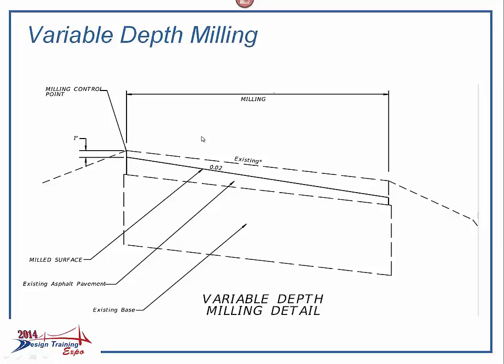The behavior of the subassembly, however, is it will begin milling operations at wherever that insertion point is and begin milling down. But a second thing to note in the behavior of the subassembly is that a friction course is always added to the top of the overlay. So if you do have a friction course, say of 3/4 of an inch, you may want to calculate your profile 3/4 of an inch below your existing ground and begin your milling from there. This seems a bit odd, but since friction course is optional, that's the way the subassembly had to be written.